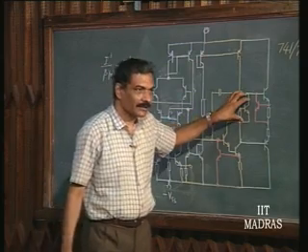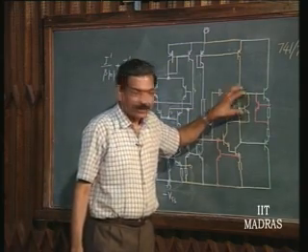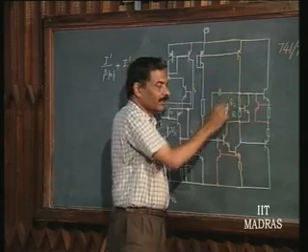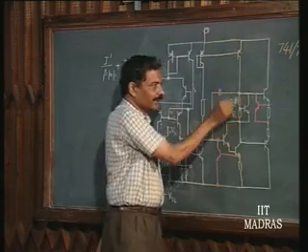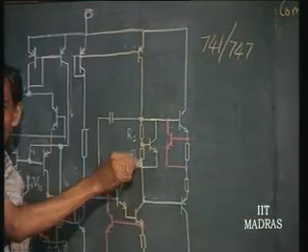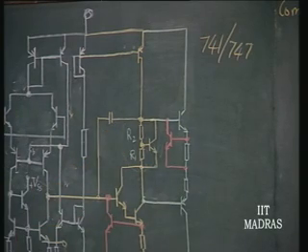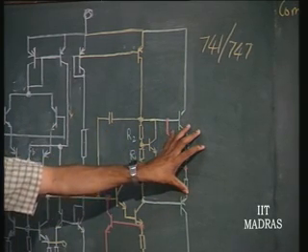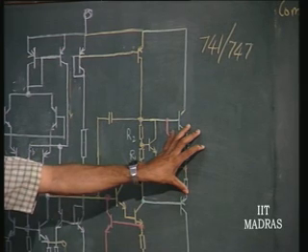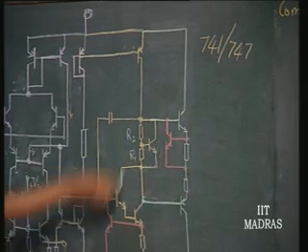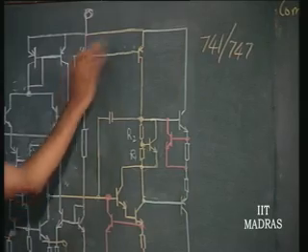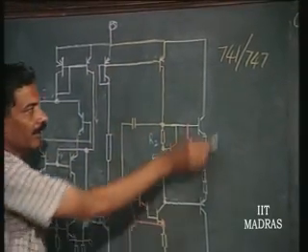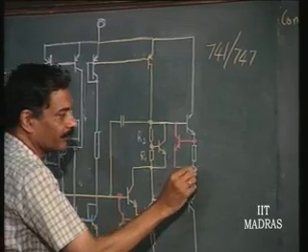This block also we had discussed. Okay. So, this gets automatically biased by this current source, okay, and therefore, the Zener voltage here is going to be less than 2 V gamma, necessary to bias the class B in class AB mode. So, this is understood. This is the active load, which is straightforward, there is not much of a difference, and this is the output stage.